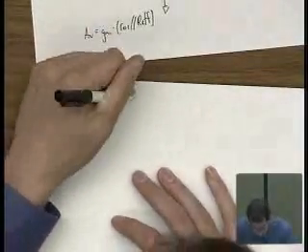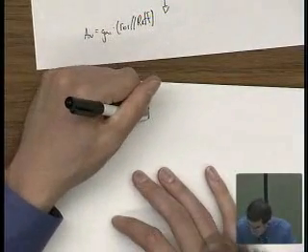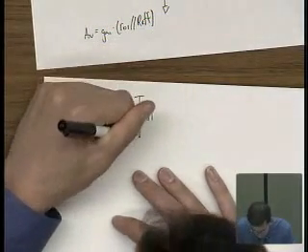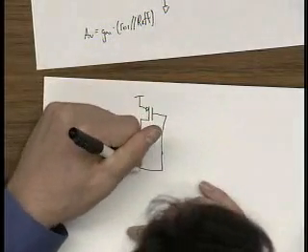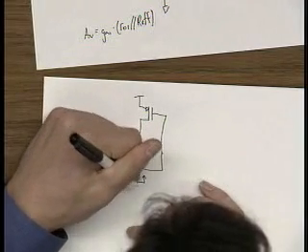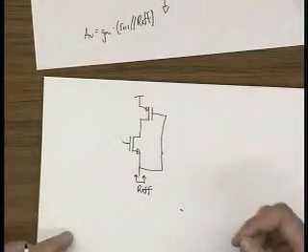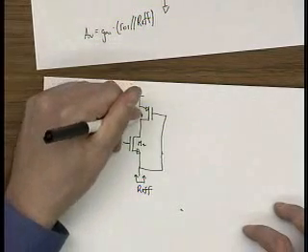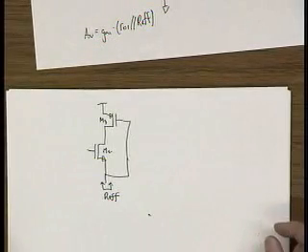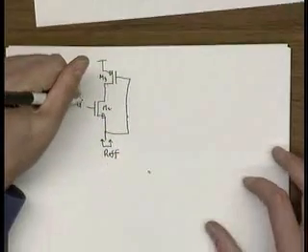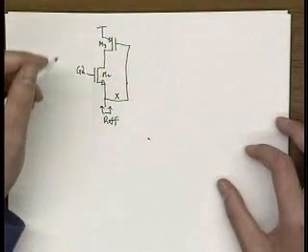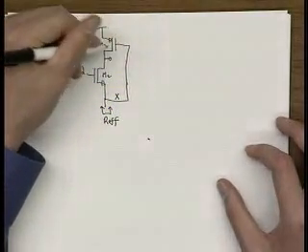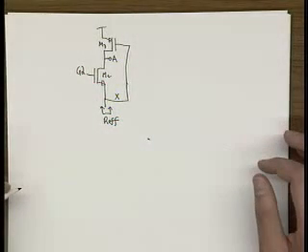So what we have now is a 2-device thing, and the nice thing is that analyzing 2 devices is 1 device easier than analyzing 3 devices. So this is the input node, R effective, right? M2, M3. So now, let's replace, and I'm going to label these nodes explicitly. This is gate 2. This is node X. This is node A. Okay?